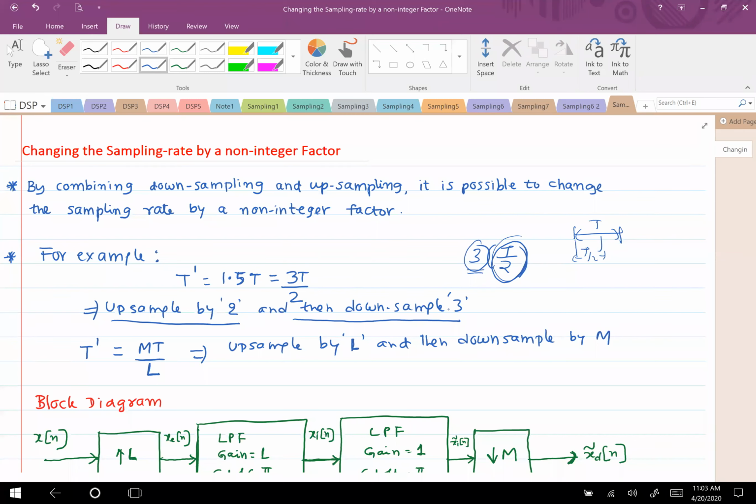The moment you are upsampling, if the discrete signal you obtained doesn't have aliasing, it means you are already taking enough samples from the continuous time signal. If you upsample it further by some factor, it would obviously never result in aliasing, since you are taking even more samples than what is required. In fact, you are dropping the existing copies after expansion and picking up only that which is required. And then downsampling is something that would cause aliasing. So obviously, you first upsample followed by downsampling.